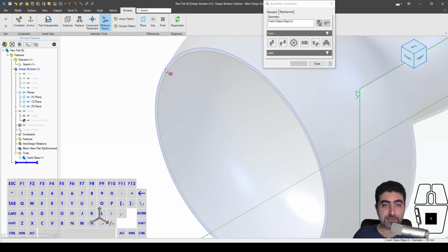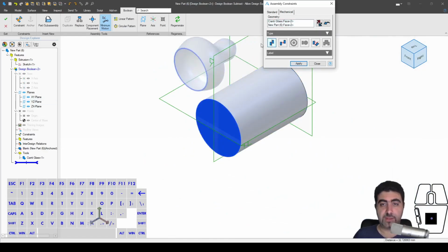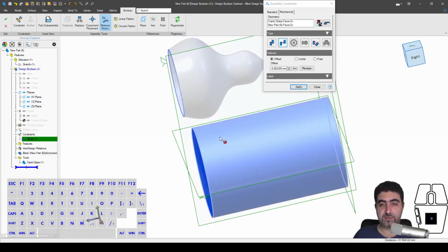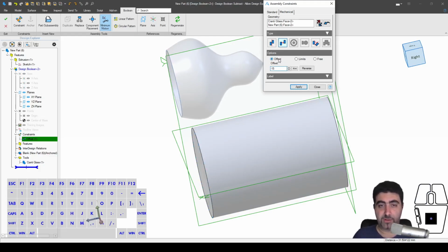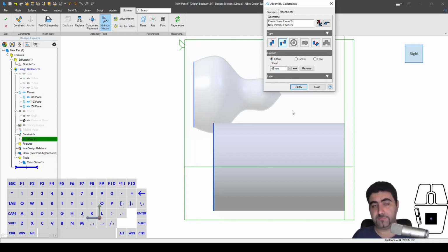Well, first of all, I actually need to select the surface, and this surface, I don't want them coincident, right? In fact, I want the surface of the cylinder, of the dumb cylinder, to be slightly below the surface there. And in fact, let's say 15 millimeters below is a reasonable amount, because maybe that's how high up you would fill it up. Let's say that I would fill this glass up to there, and no more. So what volume of fluid would I get?